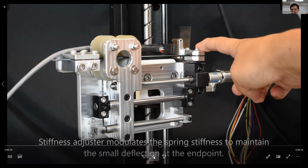When we create the deformation at the endpoint, we will have a relative translation between the brown encoder reader and the clear plastic that has a scale on it. And the linear encoder will read the deformation.